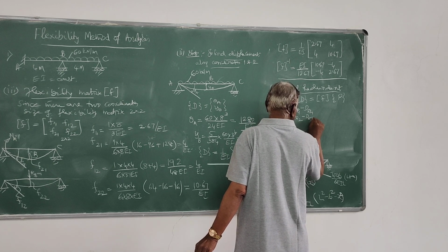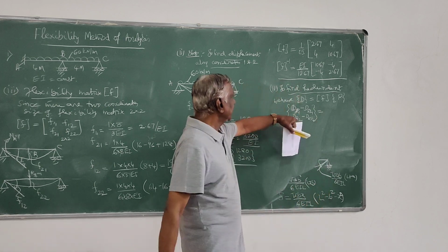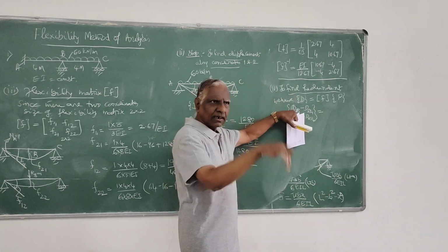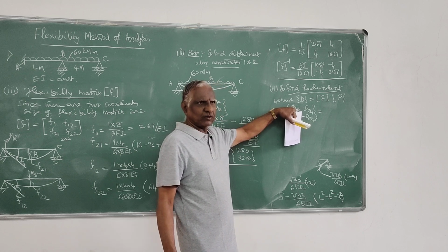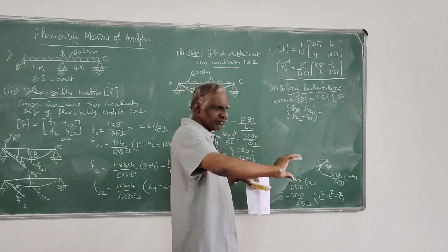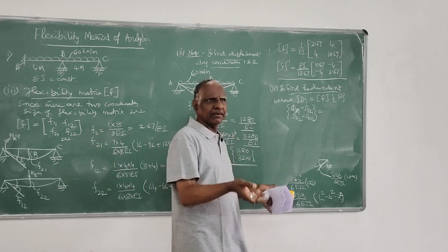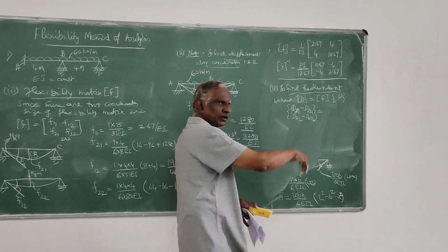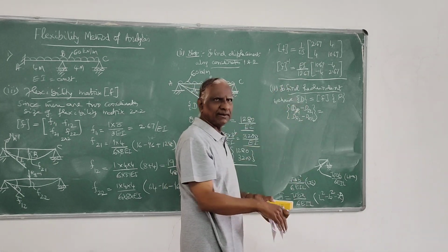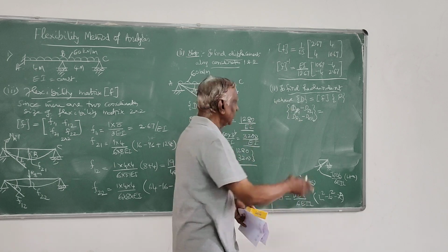I will explain what all these coefficients are. So here dr1 is external displacement vector. It is given in the problem that we have to take along the coordinate 1. If they give some rotation along that 1 forcibly, externally, then you have to take it here. Similarly, dr2, if they give support settlement, say support is settled by 4 mm or 120 by EI, that value.